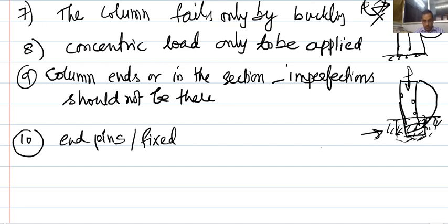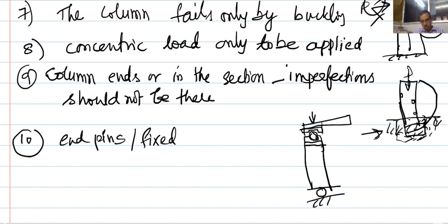That means, I have a column here, and a plate like this, on top of which I make a groove, and make a nice ball here, and also at the top I make another groove like this and fix this on the top. There is a girder here and the load is coming onto this, and similarly at the bottom I also make a kind of roller here. The roller rests in the other direction.